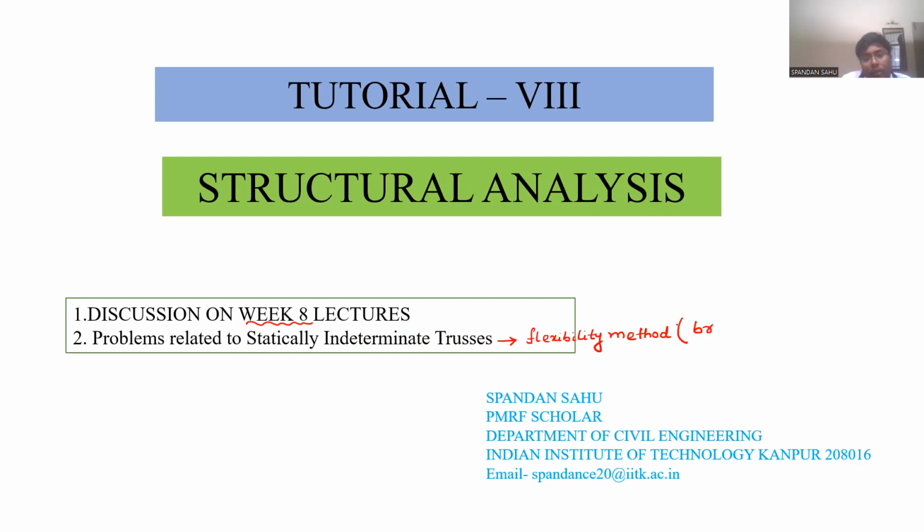Today we will just see how the components of the flexibility matrix are created, for truss members and for simple structures, truss structures mainly. We will discuss trusses today. For a simple truss structure having a lesser degree of static indeterminacy, preferably 1, how to write the flexibility component. For DSI 1 this will be a 1 cross 1 matrix, so just one component we have to write. It is a matrix containing one component only.